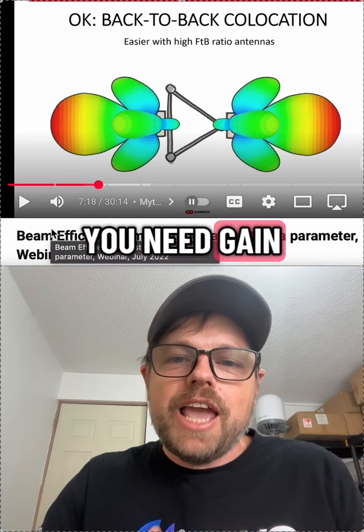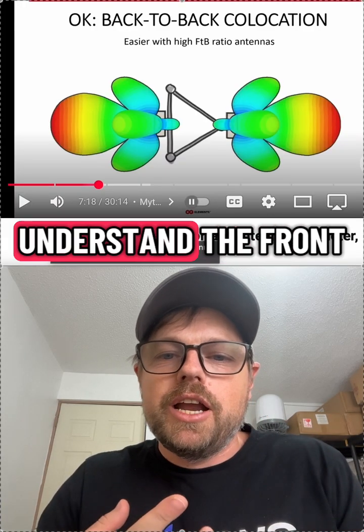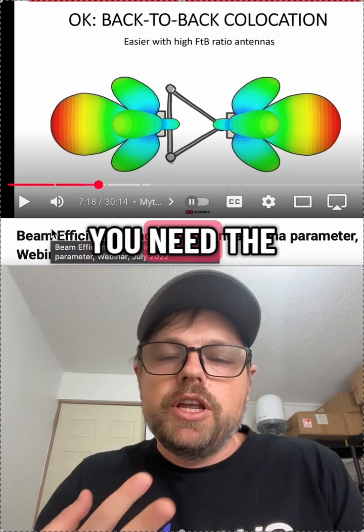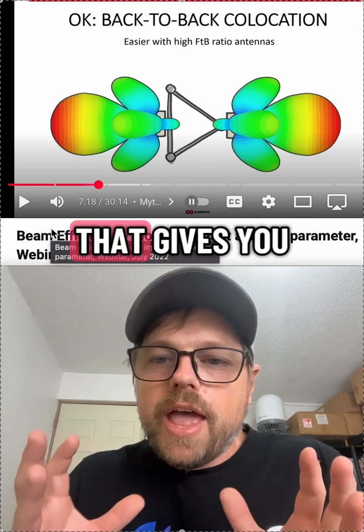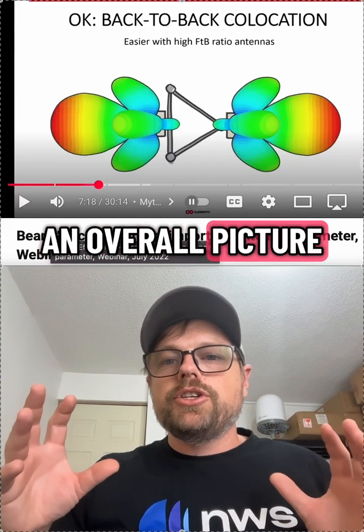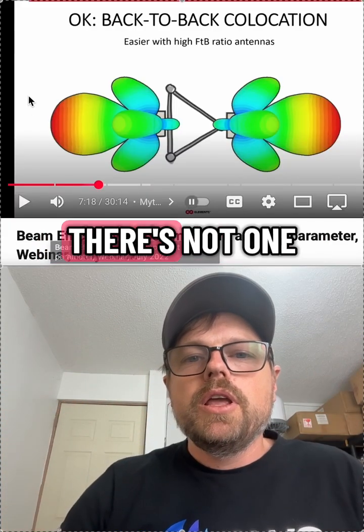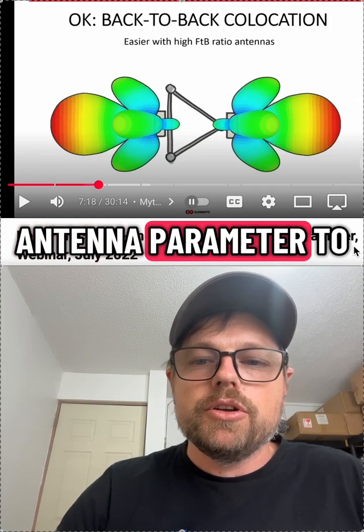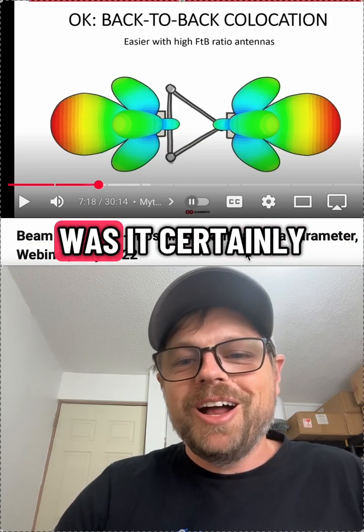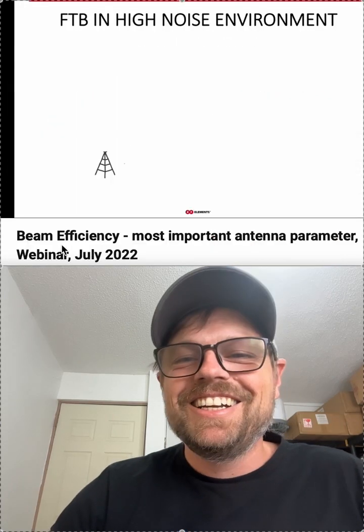But yeah, you need gain. You need to understand the front to back ratio. You need the ETSI mask. You need all of these things. You need the antenna pattern. That gives you an overall picture about the antenna. There's not one antenna parameter to rule them all. And if there was, it certainly wouldn't be this one.